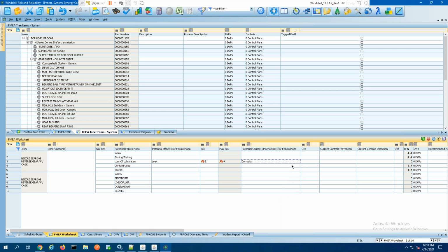And then, what would be a way to prevent that particular failure mode from occurring? So we could say, let's write in the specifications manual that this particular component should be inspected every 5 or 10,000 miles when the car comes in for service at the dealership. Now that's information that can then get into service manuals.